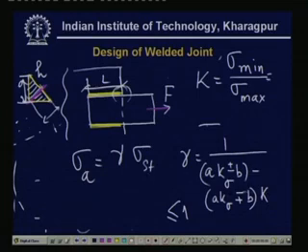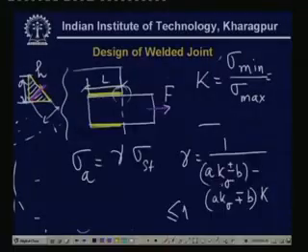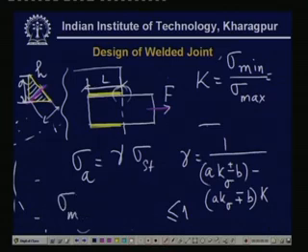So the allowable stress is gamma times St. Again, if the number of cycles is not infinite, infinite meaning more than 2 million cycles, then of course this k sigma, the corrected stress concentration factor, is multiplied by another factor, and this is how the effect of number of cycles is taken care of. Then again, the ultimate design objective is that sigma maximum must be less than sigma a. So this is roughly the procedure.